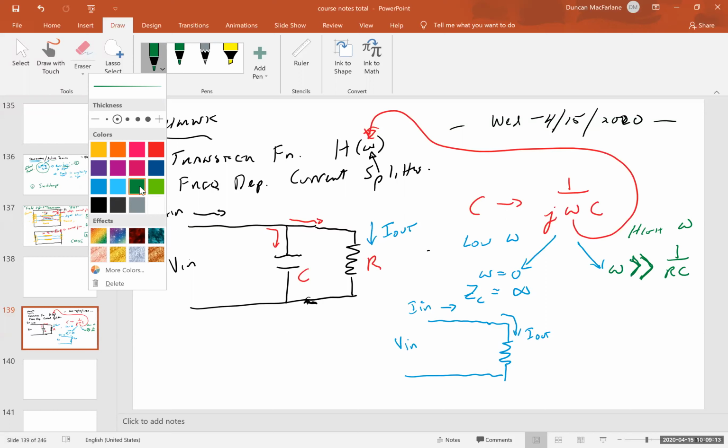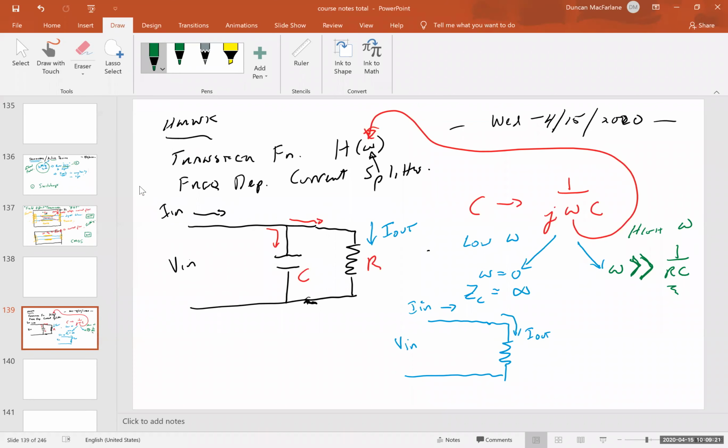There's nothing a priori in this arrangement to start talking about our RC time constant, except that it's an assertion that may be right, may be wrong. But let's sort of guess it, and if we're really wrong, well, okay, we'll back up. But I think we laid the groundwork for the high pass filter turning at a certain dimensionless number, omega RC, and we should have the same situation. So in this case, we're going to have essentially a short circuit